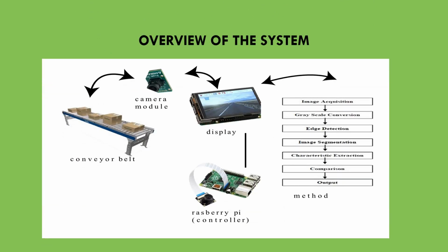Major problems we try to solve are: image processing system using cameras and image processing techniques to identify undesirable objects on roller conveyor lines. The cameras above the conveyor capture images of the passing objects. The roller background information is removed and images of the objects remain. To analyze each individual object accurately, the adjacent objects are isolated and small noisy residue fragments are removed.